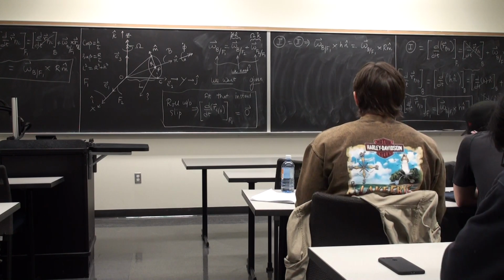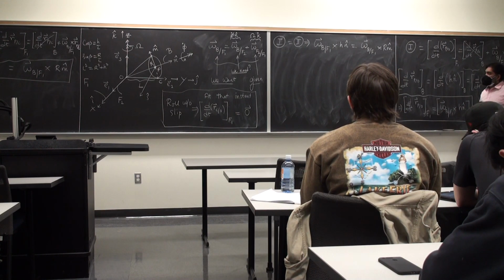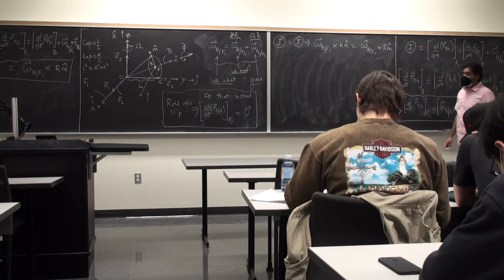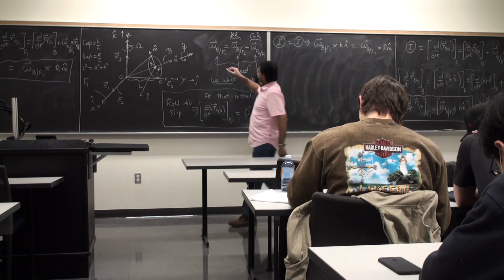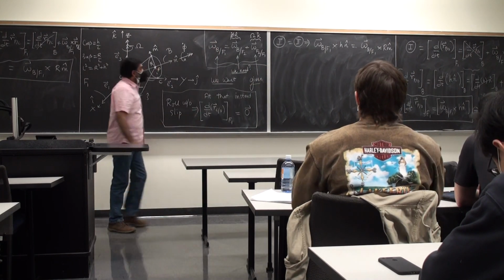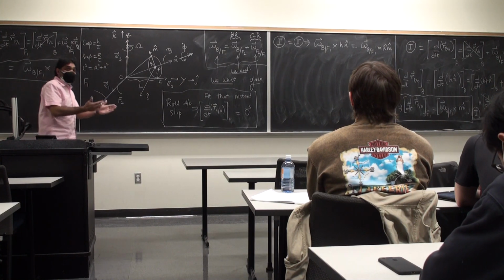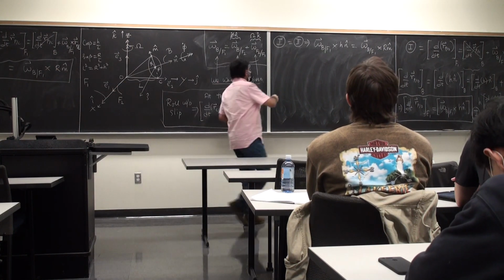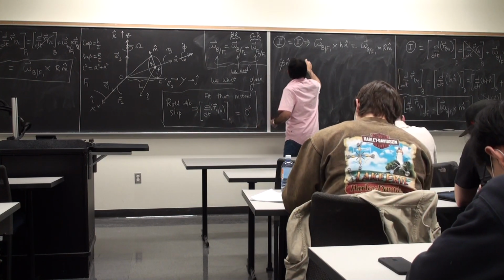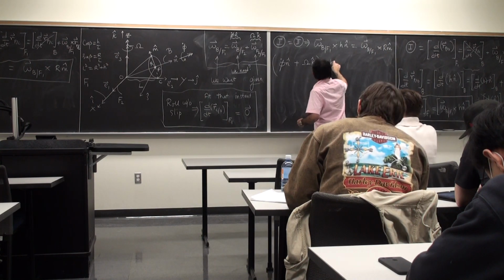And now this is just geometric manipulation, vector manipulation, that's about it. We make use of the second useful result that we have written on this board, this one here. So omega b/f1, I'm going to write it as phi dot n hat plus omega k hat.